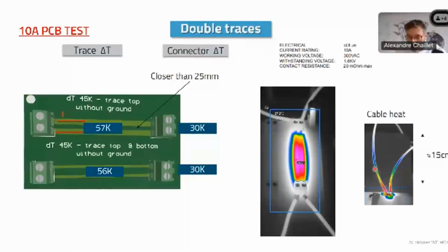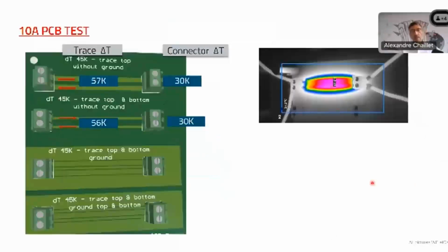And as you can see, after a while, the wire is cold. Then there is no need to have a very long cable to pull the calories outside of the PCB. Above 10, 15 centimeters, this is useless. But if you cut your wires at 5 centimeters, then it will not be long enough to cool down your PCB. So be careful. Normally, the minimum is 10, 15 centimeters.